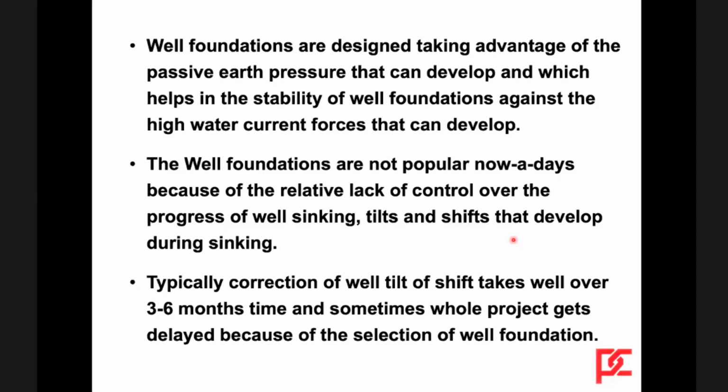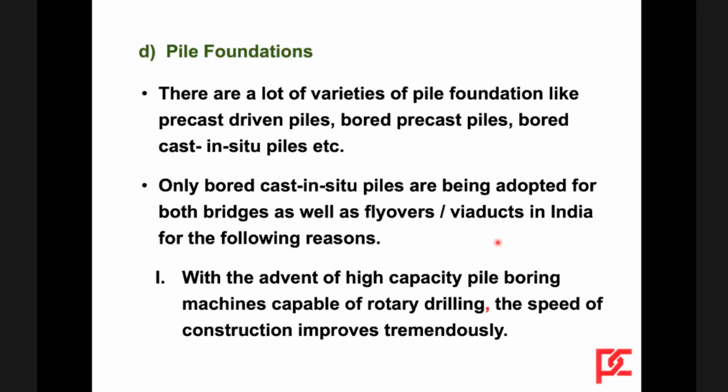But well foundations are not popular nowadays because of the relative lack of control over the progress of well sinking, tilts and shifts that develop during sinking. Typically, correction of well tilt or shift takes well over 3 to 6 months, and sometimes the whole project gets delayed because of the selection of the well foundation. That's why nowadays people are not very enthusiastic to go in for well foundations, especially because pile foundation technology has